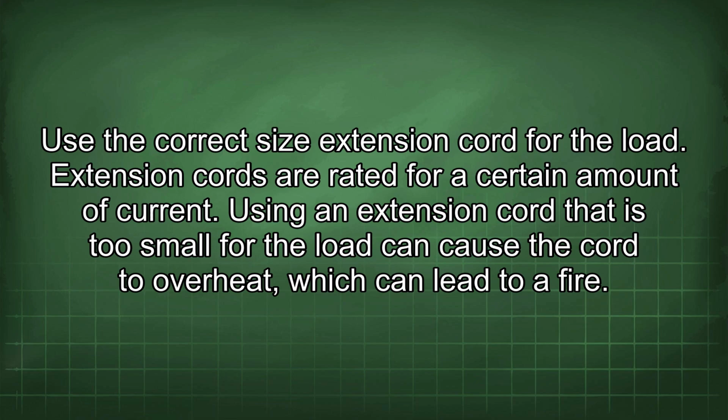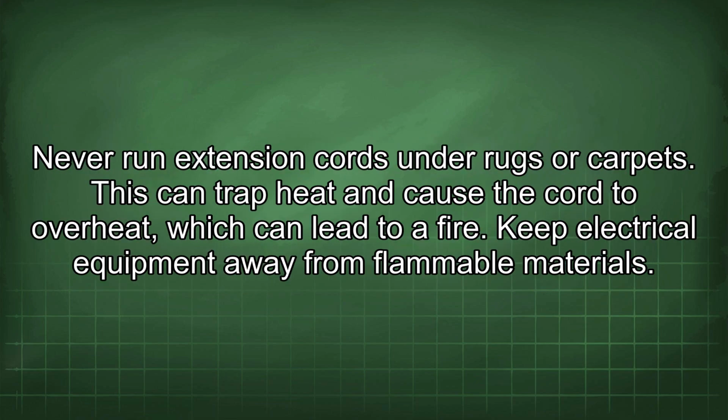Extension cords are rated for a certain amount of current. Using an extension cord that is too small for the load can cause the cord to overheat, which can lead to a fire. Never run extension cords under rugs or carpets. This can trap heat and cause the cord to overheat, which can lead to a fire.